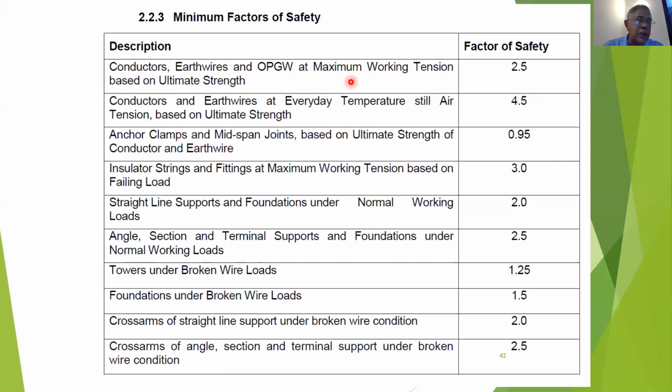For us, for design purposes we take 140 kilometers per hour wind, which has never occurred in Sri Lanka. The maximum which has occurred in past history is 70 kilometers per hour.